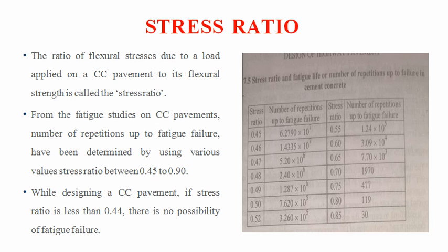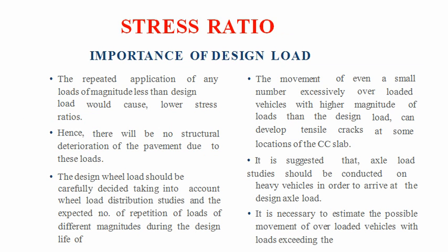From this table we can see the stress ratio and the fatigue life, or number of repetitions up to failure, in the cement concrete. So, the importance of stress ratio in the design load: repeated application of any load of magnitude less than the design load would cause lower stress ratios. Hence there will be no structural deterioration of the pavement due to this load.